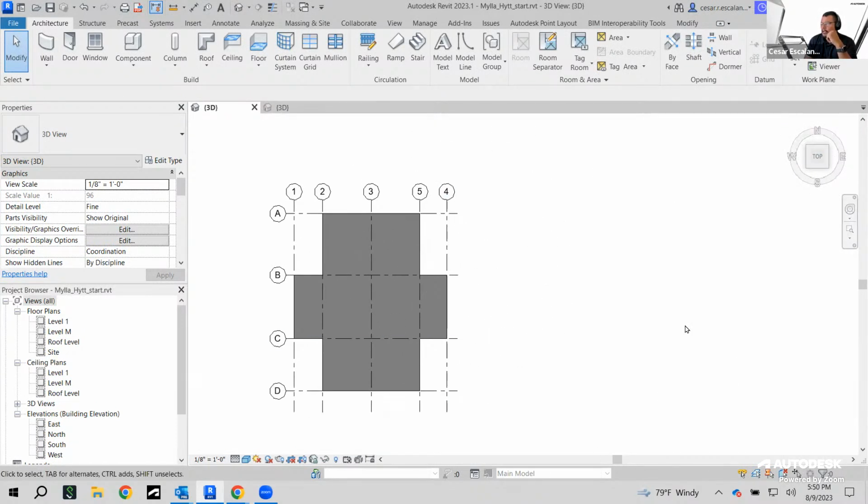And here on the right side, I'm just going to build a playground of walls. I'm going to show you some of the properties of the walls, and I'm going to use some of the out-of-the-box wall types, and then we're going to create a new one from scratch. So the wall tool is under the architectural tab, wall tool. The shortcut is also WA. You can just type it on the fly.